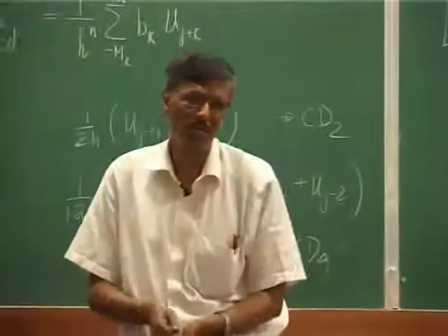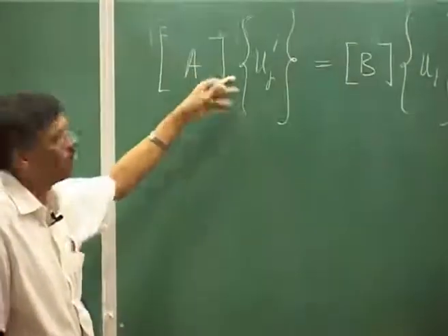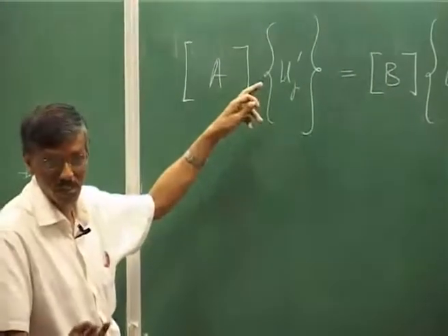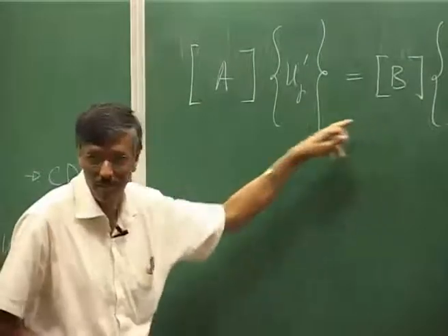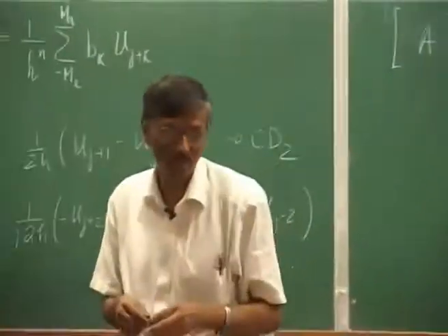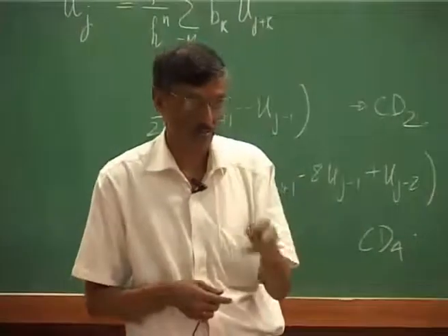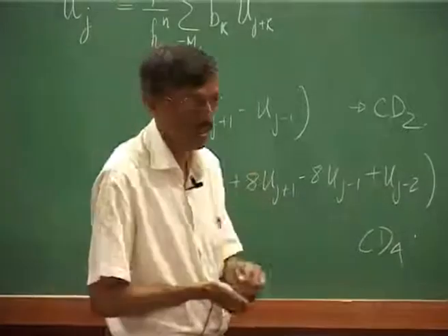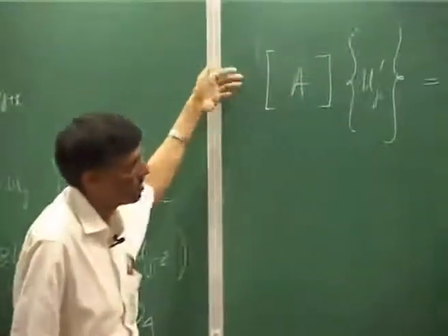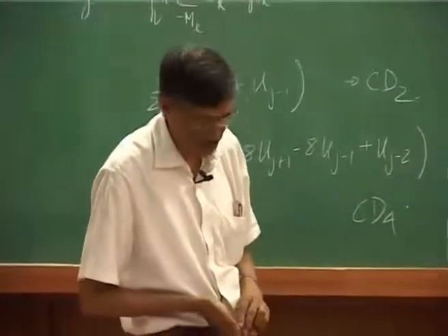Let's say if you are solving a 2D flow problem, you will probably have 2 components of velocities, and each one will have 2 derivatives, so you will have to solve 4 sets of equations for calculating del ux del x, del ux del y, del uy del x, and del uy del y. So we'll have to be executing this step for 4 such derivatives.